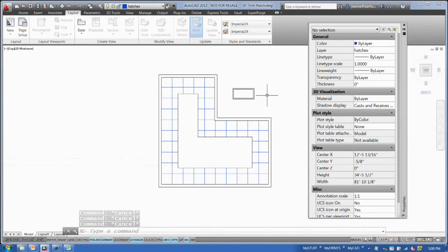You should always be able to trim a hatch. I have an older template that some people are using. The question doesn't have a variable. I'd have to look at that. The question was, what system variable keeps that from hatching or from happening? I'm not aware of one that keeps it from trimming, but there's a O-snap hatch that allows you to snap to a hatch. But send me an email after and I can look at it.